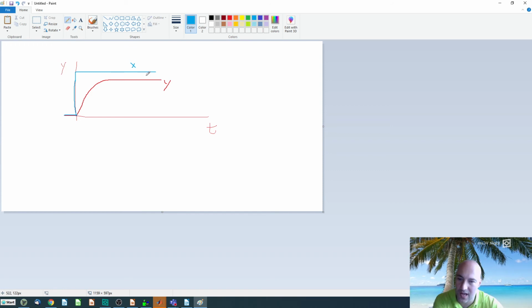It does not have to go to the same value, because you can have a different steady state for y. That depends on the system. So like this, we will get a transient response in Simulink. In order to repeat the experiment and keep it running, the input will not be just this step function, but a rectangular wave, like that. This means you will have another transfer function, but now it will go to 0. So like this, you will create that in Simulink. This is fairly easy.